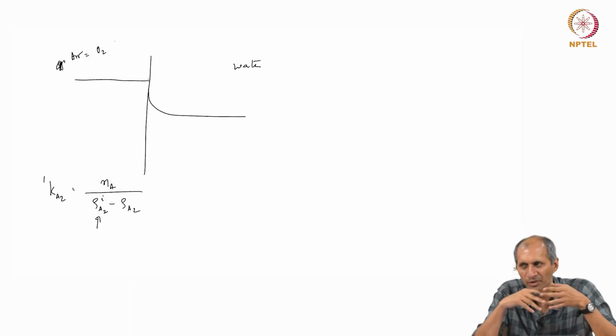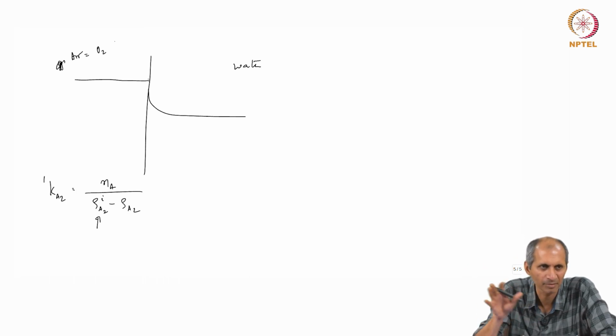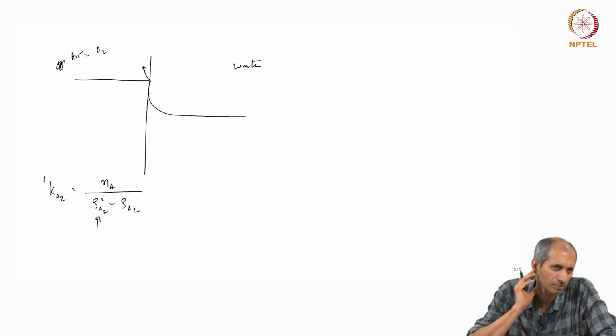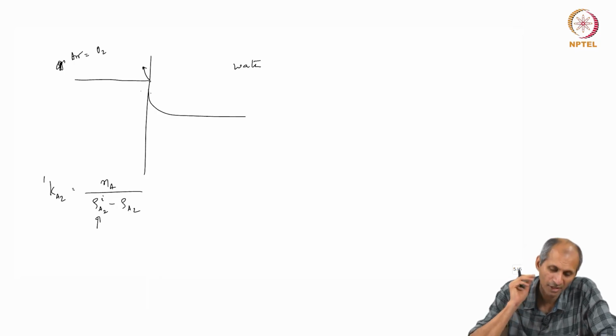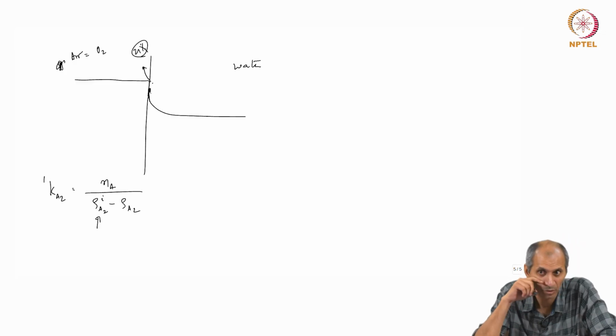It is not a solute that you introduce somewhere and it goes. The composition of the atmosphere is such that oxygen is not segregated in one pocket of air. So, it is throughout the same. The concentration of oxygen in air is known and its solubility inside water is known. So, we start with the solubility of oxygen in water and that is the gradient that we draw. It is 21% oxygen in air, that is already known. Correspondingly there is a water concentration that is known, and this is what we use in this case.